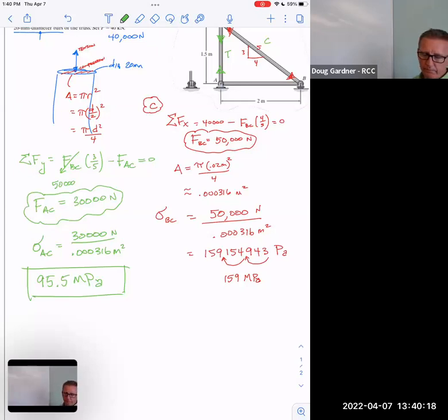Mistakenly, I just did the stress. So I did F of Y, but with stresses instead. And I got the same answer. Oh, interesting question. In other words, he took this number and used that number and made this calculation and got 95.5 anyway. Yeah, so 159 times 3/5, I got 95.4. So it's like a rounding thing. Yeah, that's totally true. That's not a fluke. Now that worked because all these bars are the same size. If the other bar had been a different size, then we wouldn't be able to do that.